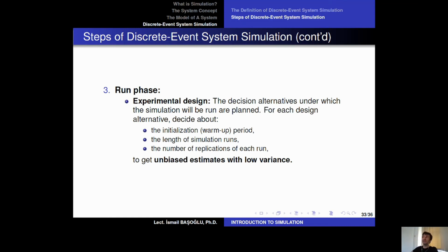If you take statistics over the overall time, you are also collecting statistics from the beginning, where the system was empty. So we remove that warm-up period from our statistical analysis, and we look at the statistical results in the steady state of the simulation, where the supermarket has lots of customers and scheduled cashiers, and so on.